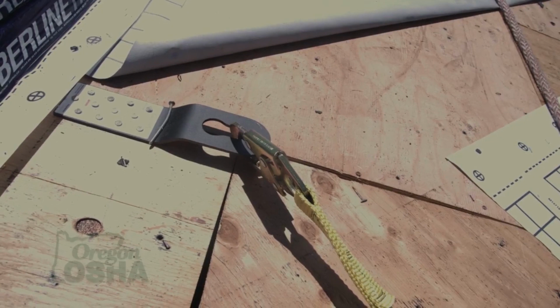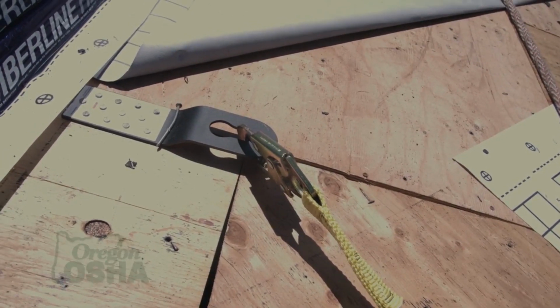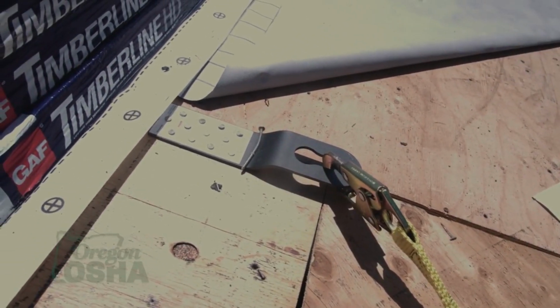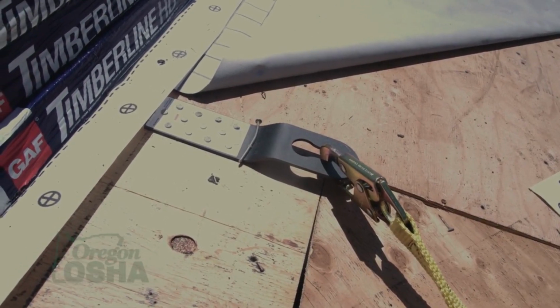So there's multiple types of anchors. You can anchor in different positions, depending on the roof that you're working on will kind of dictate the type of anchor that you need to use. We call them brackets. There's a multitude of options when it comes to tie-off. You've got hitch clips, you've got the full double-sided D-rings, you've got the single-sided D-rings, you've got the rafter brackets that you can attach, especially on new construction. Some of them are permanent, some of them are temporary.